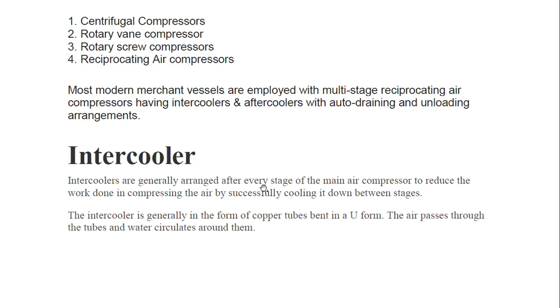So when we talk about intercoolers, it is generally arranged after every stage of main air compressor. Generally we have two stage air compressor to reduce the work done in compressing the air by successively cooling it down between stages. Because generally when anything is compressed, the temperature rises. If you see the temperature curve, then it will rise when you compress in a confined volume.